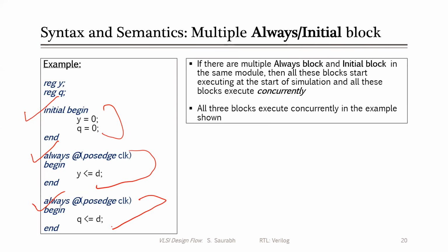So what this ensures is that if you actually make that hardware, your hardware is designed properly, and it is not dependent on the order of execution. It is independent of the order of execution, right? And that should be how hardware is designed, because if you have multiple blocks of hardware running in parallel, you cannot control which one will be executed first.